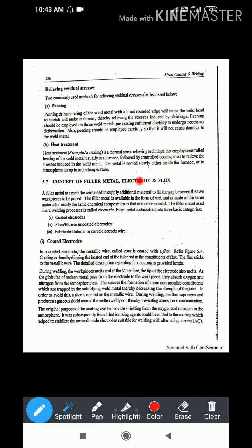See, once the welding is done, the welded material or workpiece is heated again by a fire flame, torch, or in a furnace. Then it is allowed to cool rapidly, meaning fast, by spraying water or air or sprinkling coolant on it, so the residual stresses are removed.